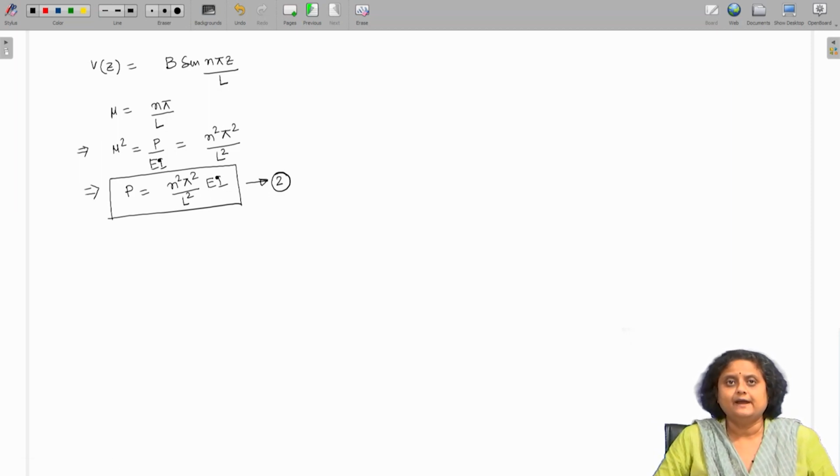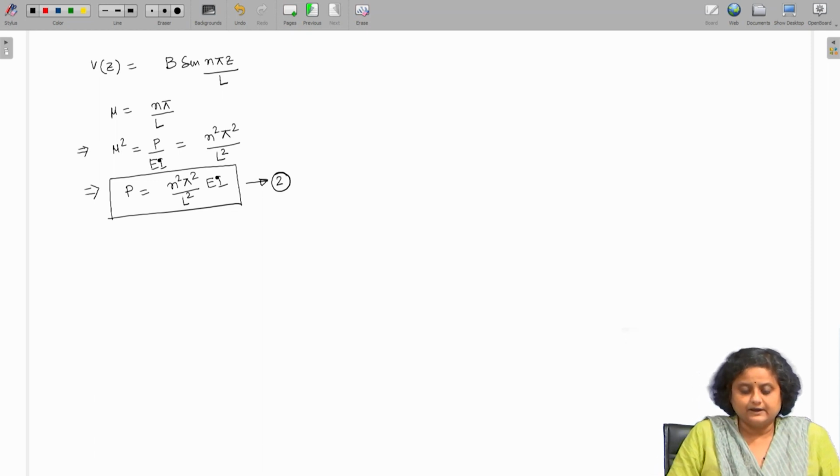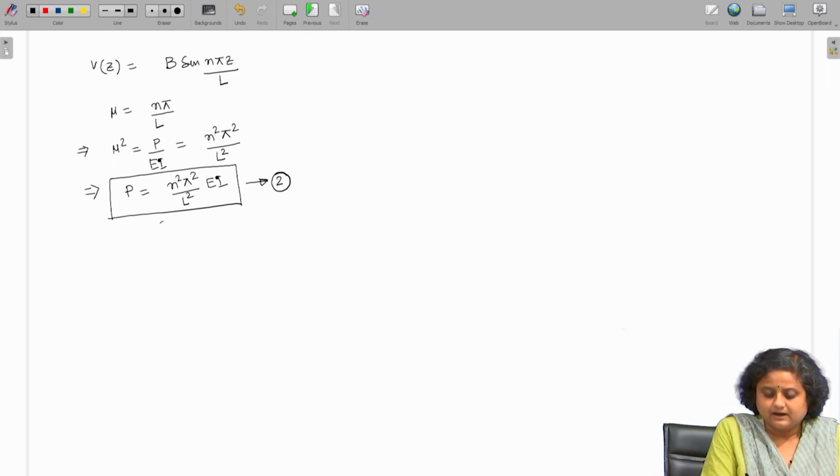Therefore, if P is equal to this value, then it is possible to have a lateral deformation, and it is going to be a stable lateral deformation, because it is in the equilibrium condition. Therefore, these are the critical buckling loads of the pin column.